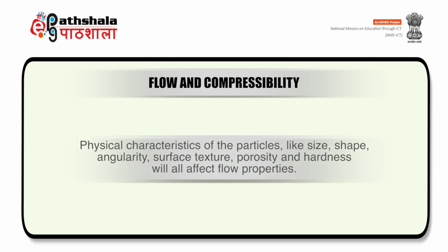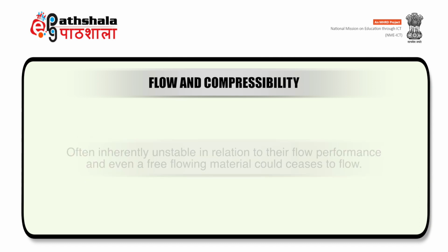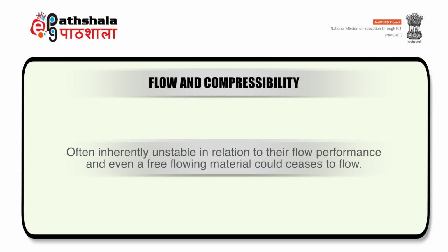Physical characteristics of the particles like size, shape, angularity, surface texture, porosity and hardness will all affect flow properties. External factors such as humidity, conveying environment, vibration and perhaps most importantly aeration will compound the problem. Another characteristic of powders is that they are often inherently unstable in relation to their flow performance, and even a free flowing material could cease to flow.